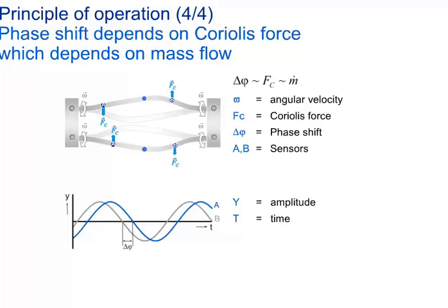Overall, a double tube meter shows a much better accuracy on both mass flow rate and density measurements due to the stronger signal, a much better turn-down ratio, and is less sensitive to external noise sources. We will talk in greater detail later about the differences between single straight tube and double tube designs.